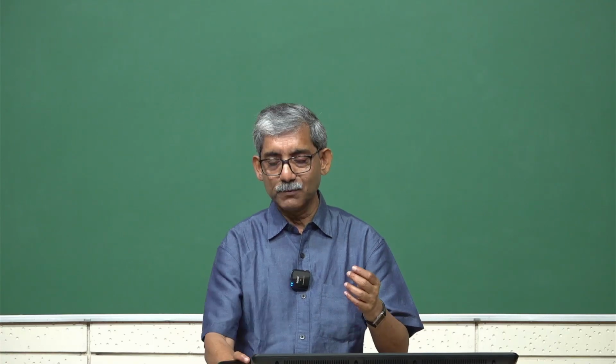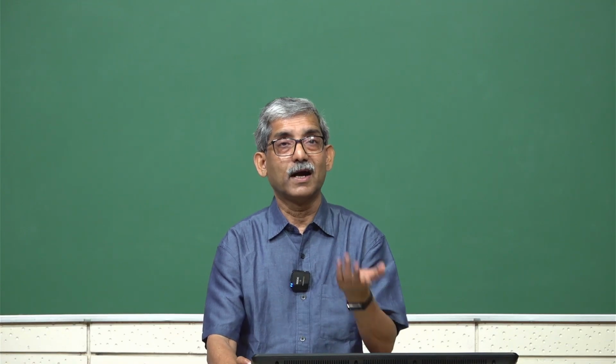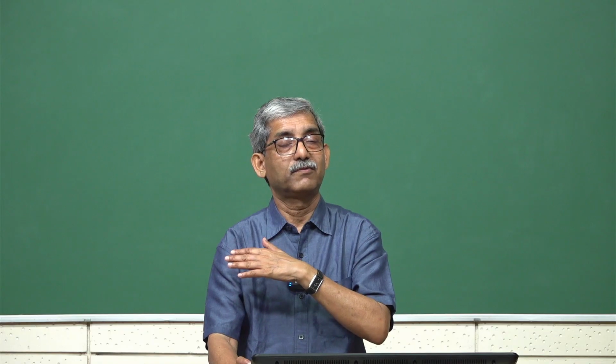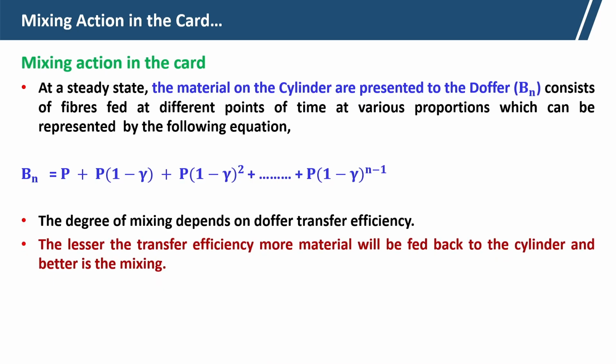For proper opening, if we do repeated carding, then the fibers get segregated properly. So, the lesser the transfer efficiency, the more material will feed back to the cylinder and better mixing will take place.